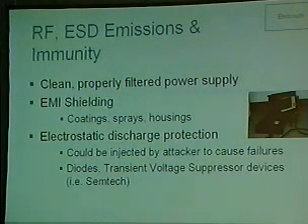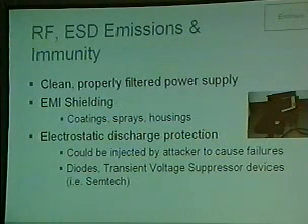What you want to do is reduce EMI in your system, mainly because of TEMPEST monitoring, which is basically recreating EMI for monitors or keyboards, recreating the signal on an external monitor, an external device of some kind. The simple explanation is that as voltages are applied to the CRT of the monitor, there are spikes and high voltages that generate this noise, and it creates detectable spikes that could be recreated.